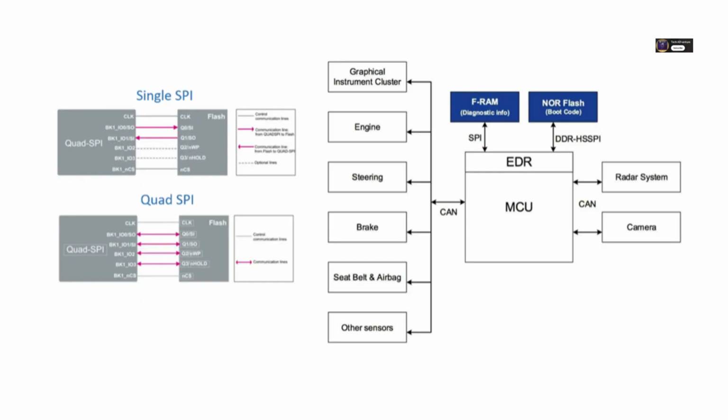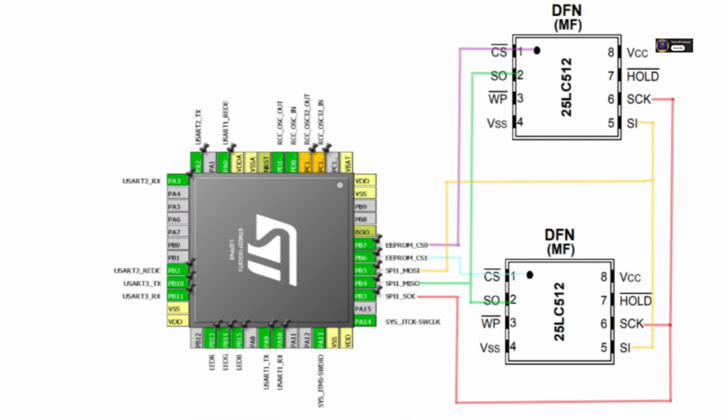Wow, that's incredibly detailed. Super helpful. Okay, thinking about all those steps, what are the absolute most common pitfalls or gotchas that trip people up when they're trying to get SPI flash working reliably with, say, an STM32? Oh, there are definitely common ones. Number 1 is probably getting the CPOL CPHA settings wrong. Always double check the data sheet, usually mode 0, but verify.